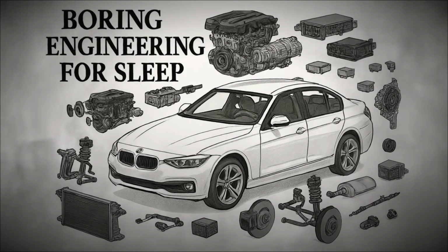The fuel tank is the storage container, mounted usually at the rear of the car, designed to safely hold gasoline or diesel while protecting it from leaks, impacts, and evaporation. Modern tanks are often made from high-strength plastic that resists corrosion and reduces weight, though older vehicles used metal tanks. Inside the tank are baffles that reduce sloshing when the car moves or corners, and most tanks also contain a fuel level sensor that sends information to the gauge on the dashboard.